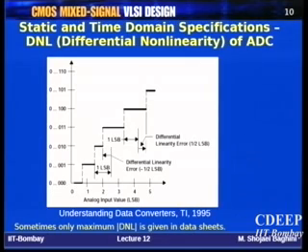Still, there is one more thing regarding static characteristics, which is nonlinearity: DNL and INL. DNL and INL are well defined in all the literature. Here I have used a very old reference, but it is a good one. That's why they call it differential linearity, but actually it is differential nonlinearity. Of course, some textbooks still call it differential linearity. Eventually, what does it mean? The same thing that we discussed now, in a more precise way.